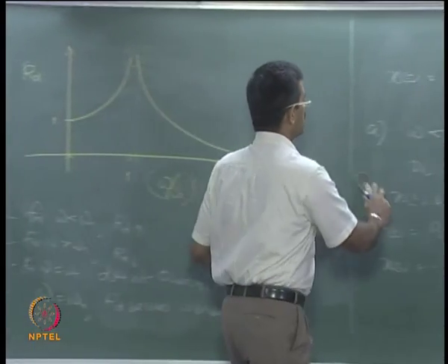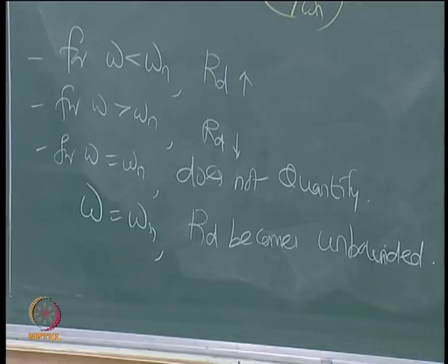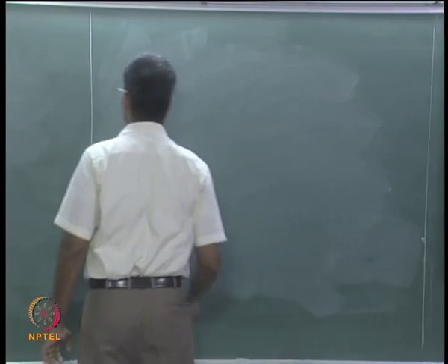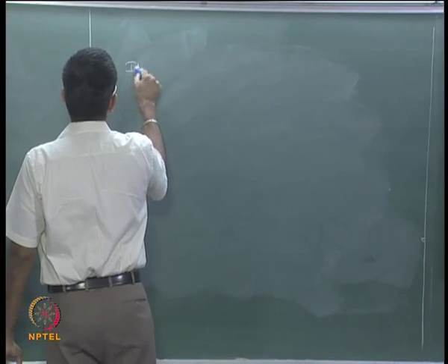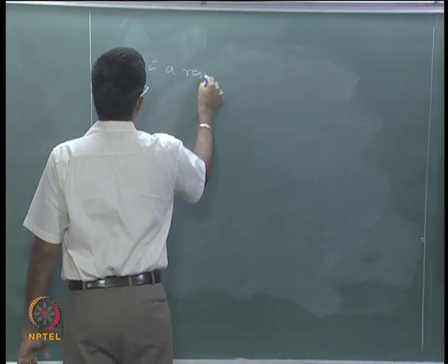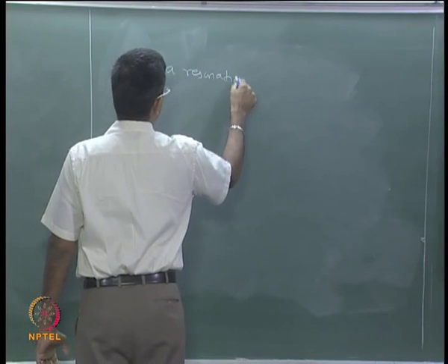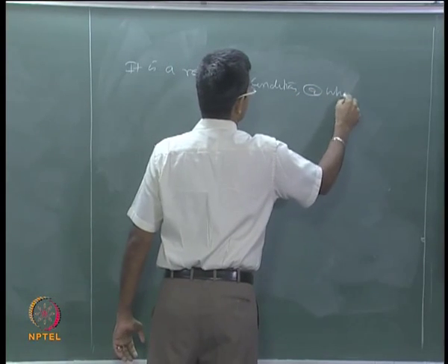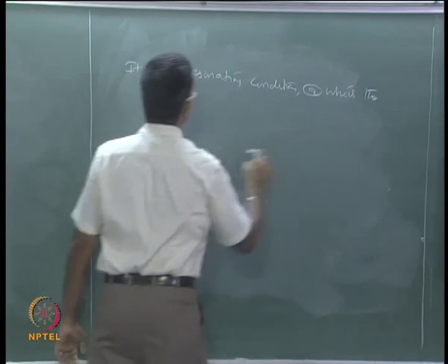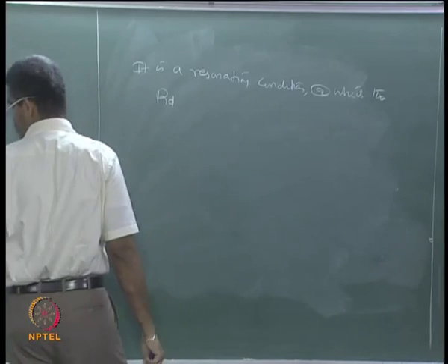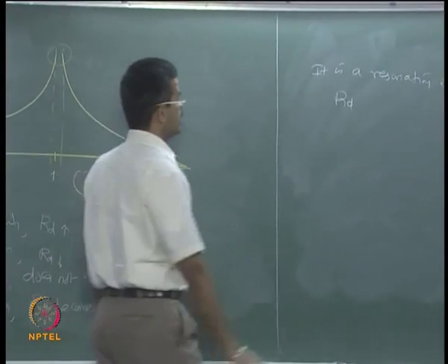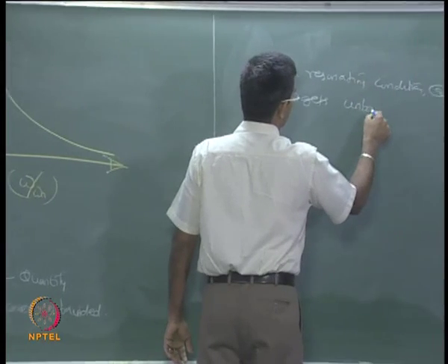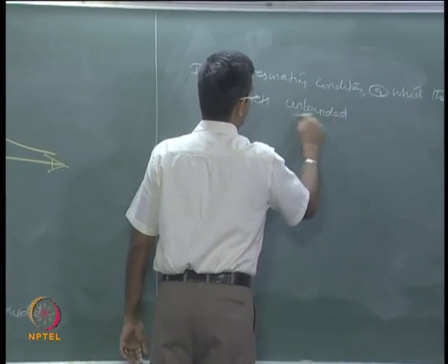Now, let us define this state in the analysis, saying it is a resonating condition at which the dynamic response factor, or sorry, the deformation response factor becomes unbounded. I am not saying infinity and all, it is unbounded.